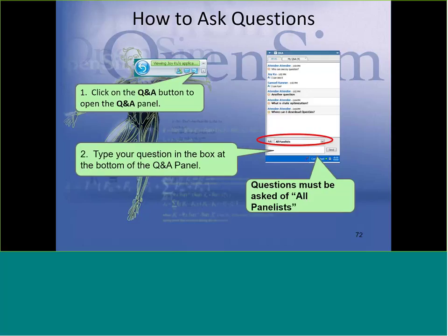So you can download our model and look. We didn't want to add wrapping. I felt like Apoorva had done a really good job to try to simplify some of the wrapping that had been there in Edith Arnold's model, because the more wrapping you have, the more it slows down your simulations. So Apoorva did a really good job of using a minimal set of wrapping, and we basically just tried to tweak those, or maybe even get rid of some, like at the biceps short head, where we actually got rid of a wrapping surface to better match measured EMG data.